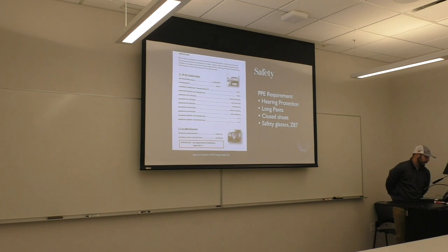Maximum air pressure is 160 psi, and minimum air pressure is 100 psi. Maximum ambient air temperature is 41 Celsius, and minimum is 0 Celsius. But while we run the experiment, we shouldn't come close to these limitations.